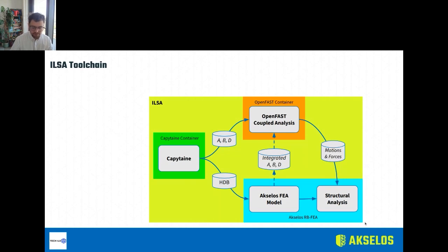And this makes it possible to accurately, robustly take all the loads from the coupled analysis and map these onto our FEA model. So that includes inertial loads, acceleration, force loads, tower-based force, mooring line forces, as well as hydrostatics, radiation, diffraction, and Morison loads.